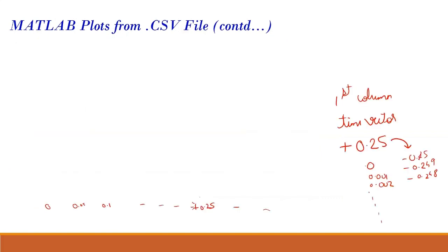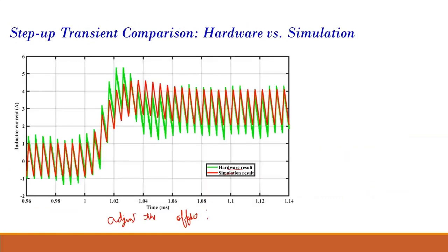You're talking about this one? Yes, sir. The IL min is matching. The instant at which IL min happens in both the waveforms is matching. The instants will be the same because it is fixed frequency operation. This time duration is fixed, so when it turns on, it can be synchronized.